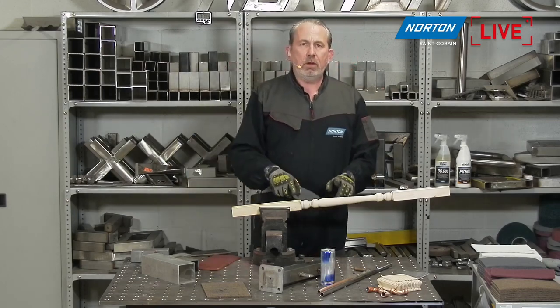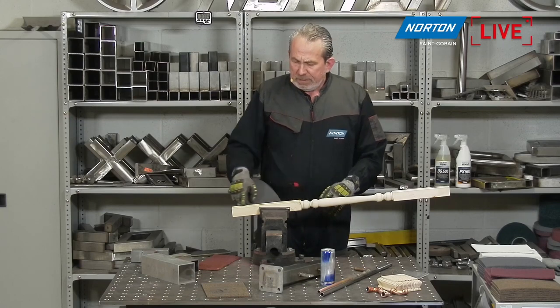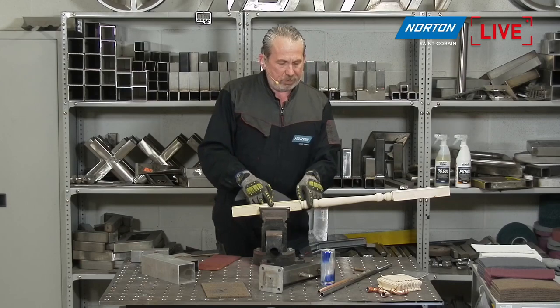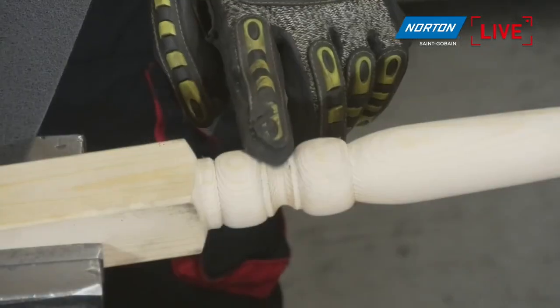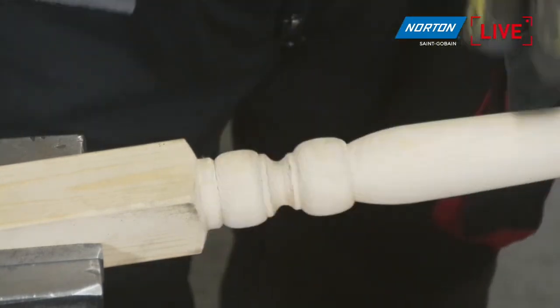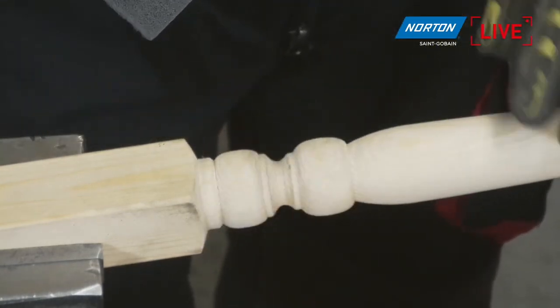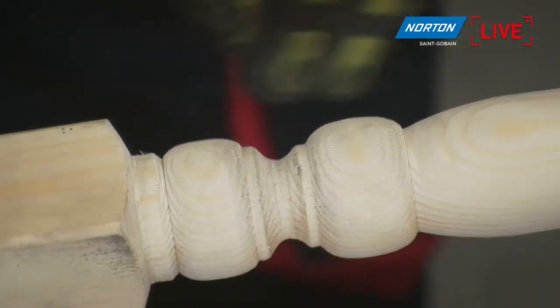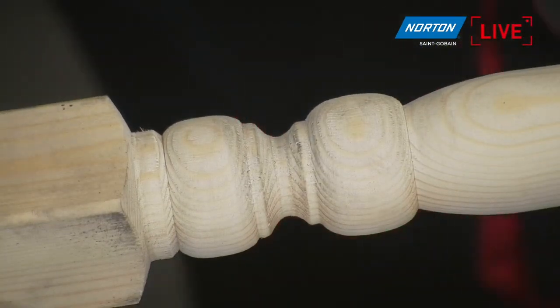These are actually turned on a lathe with a wood turning tool. Now, the flat parts are normally okay, but where the actual turning tool has been creating a shape inside this material like we have here, we can see it's a bit rough. You could paint that straight away and it would look okay, but you'd still see some of that rough machining mark on that wood if you don't sand it down.